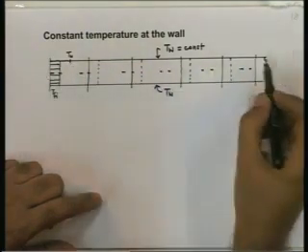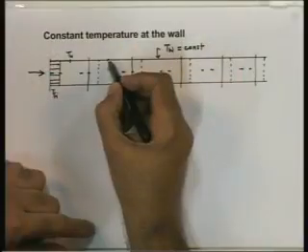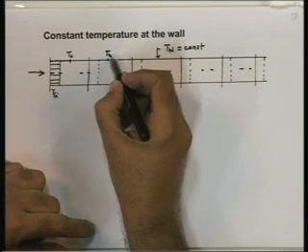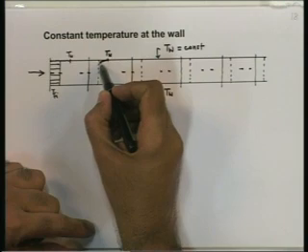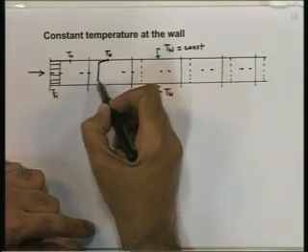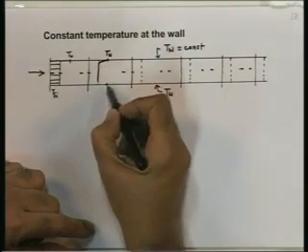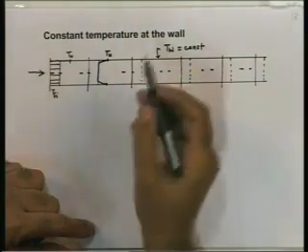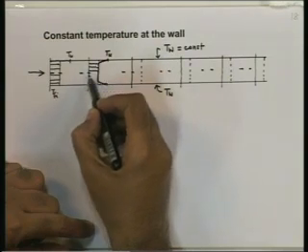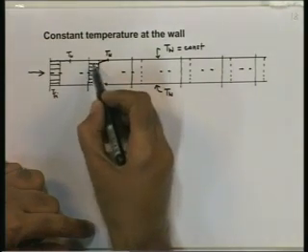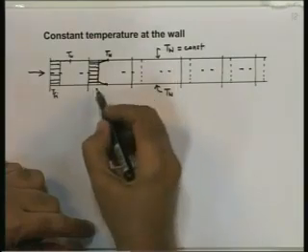The heat transfer will continue as the fluid flows. After a short distance, the fluid layer near the wall would have reached the wall temperature, but the effect of the wall temperature would not have penetrated significantly into the fluid. The fluid temperature over much of the cross section would remain equal to Tfi.